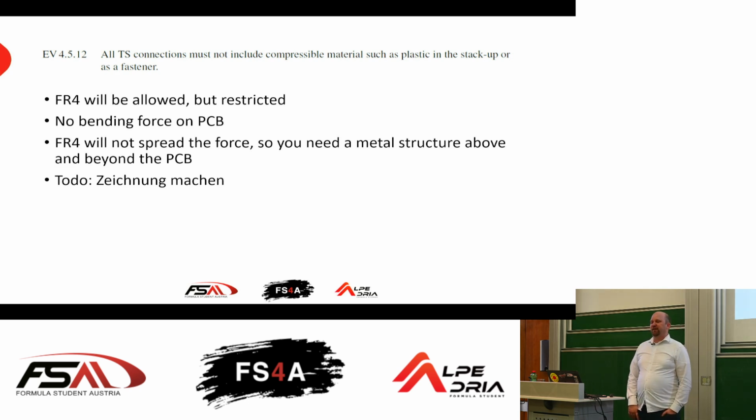stack their accumulator PCBs. They have one PCB, then over there's the cell tabs, and over there's the bus bar. And all secured with one screw, and the PCB will bend a little bit, and then you have the force only at one point of the cell tabs, and that's simply not allowed. That's simply not okay.